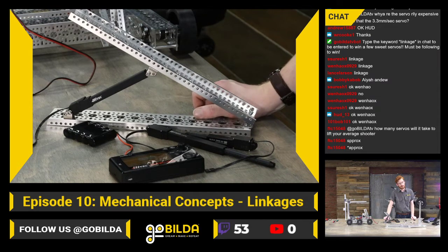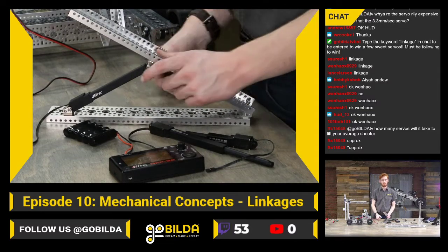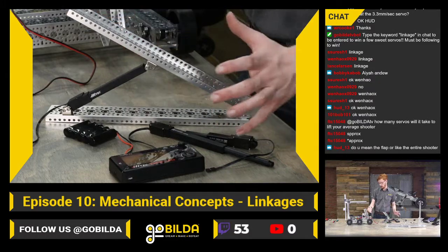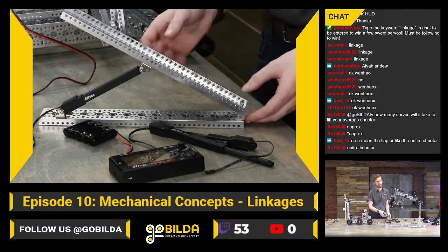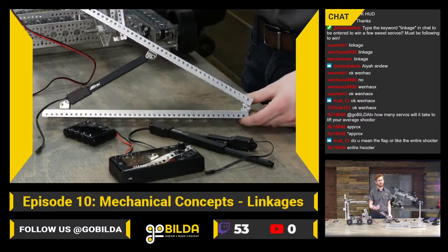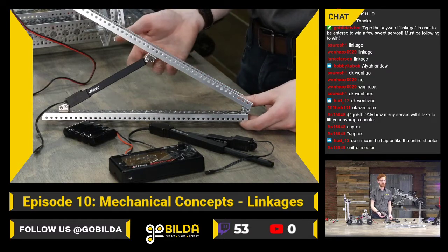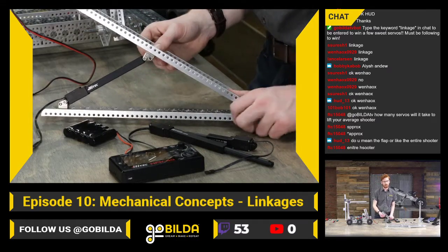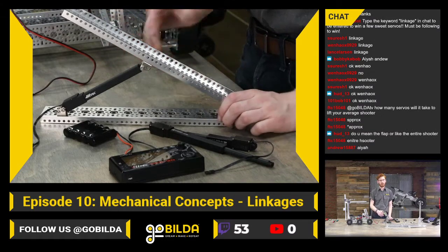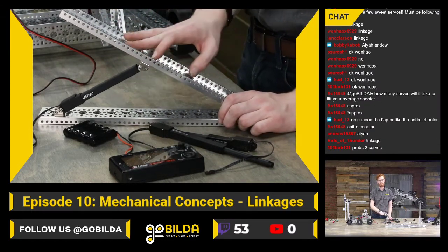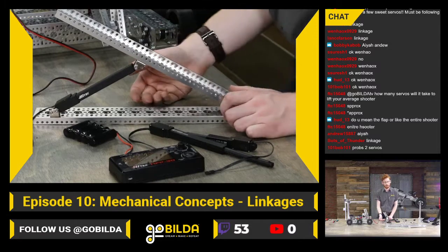All depends on the amount of weight there. You should be able to calculate it. You can look at it as the same torque equation that you would use all the time. So if your shooter is mounted on a mechanism like this, the best case scenario is to use CAD to find the center of gravity, and then measure the distance between the center of rotation to the center of gravity, and that's going to be your lever arm length. And your lever arm length times your weight will give you your torque. So in this case, if that is a 6-inch arm and you have a 1 pound shooter, you're going to have 6 inch-pounds of force that you're going to need to lift up.